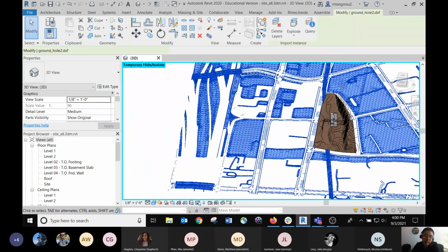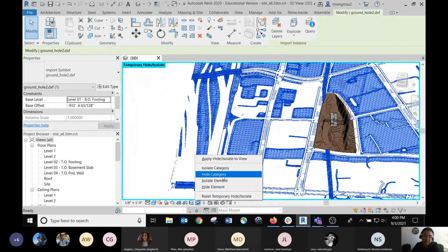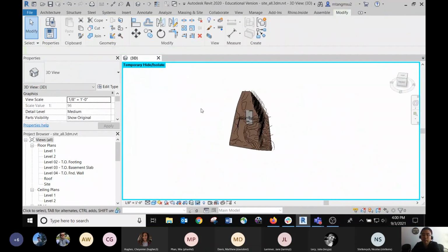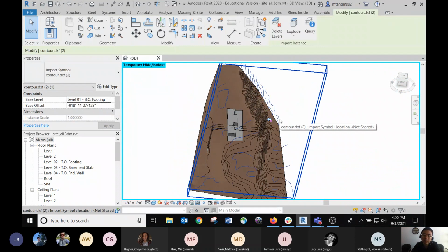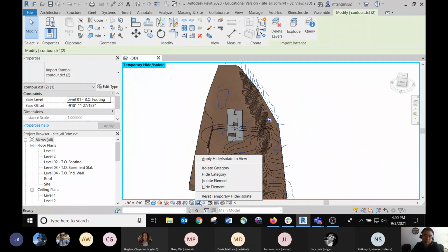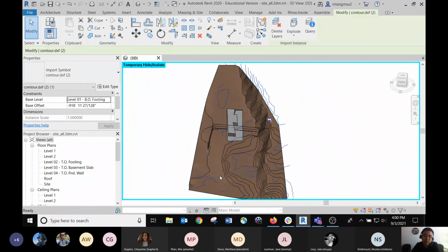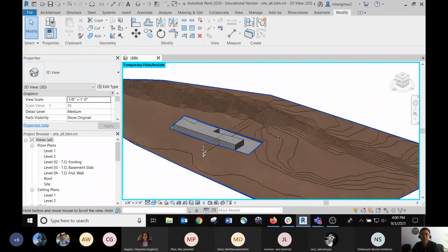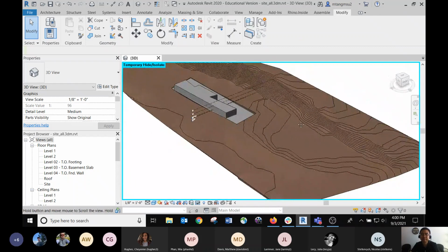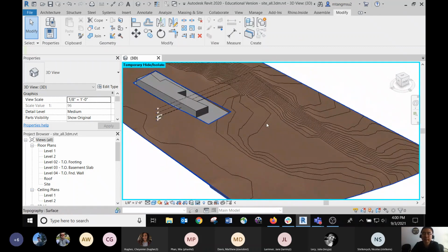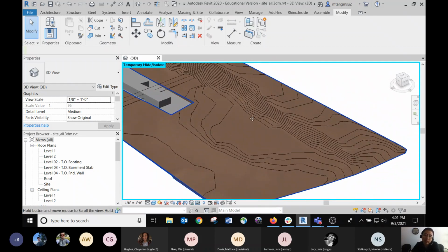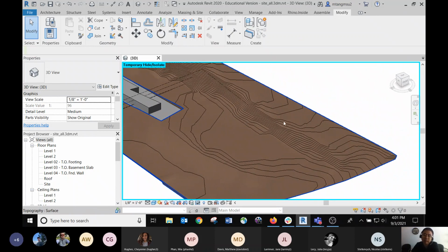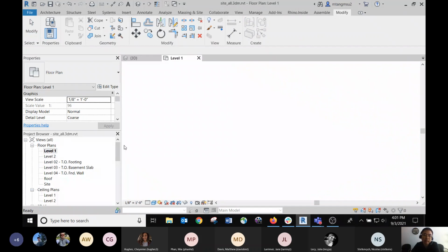Okay. I also want to hide maybe this topography. All right, that's better. I don't really need to see these contour lines. Let me hide them. Okay, so this is pretty clean. I have this only in the topo surface, right? Then let's go ahead and create something for project 3. So I will start probably with the building pad, right?